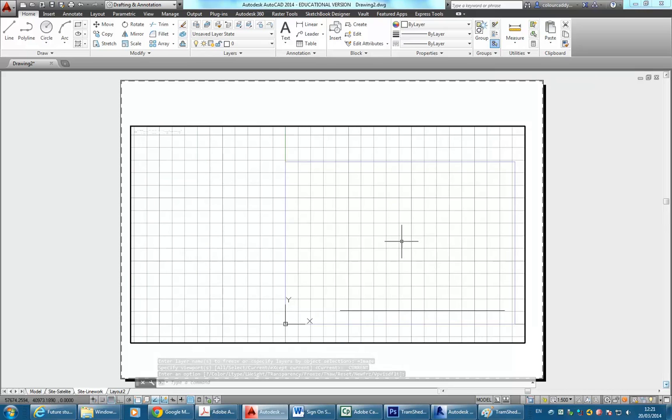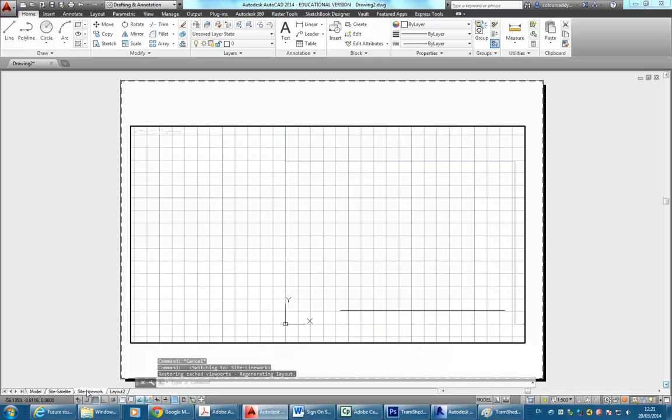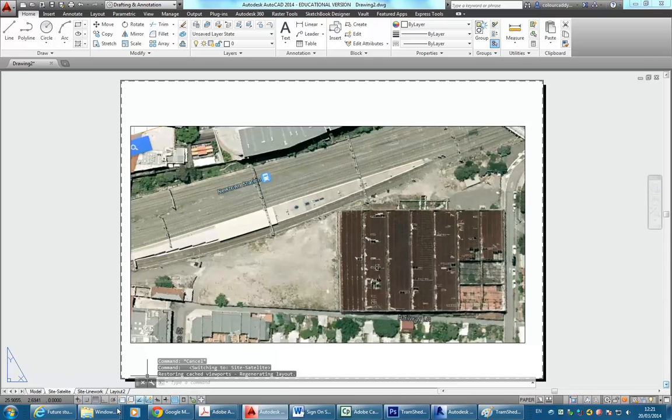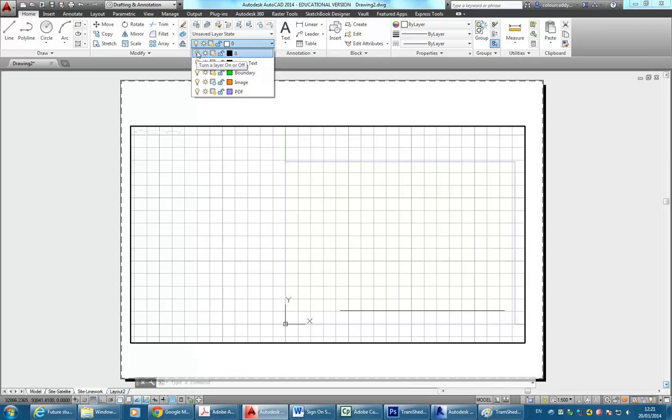Okay, so that's a really, really useful thing. So it's kind of like Revit now. I've got one view with the image on, one view with the image off, and that can make it much easier when you're working. No. See, because the light bulb would turn it off in all the views, and so would the regular freeze. That's why you've got to use the special viewport freeze.